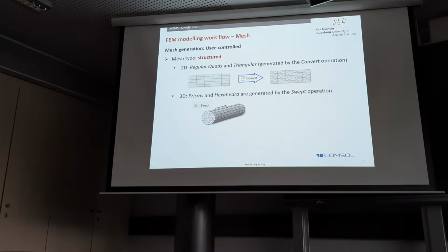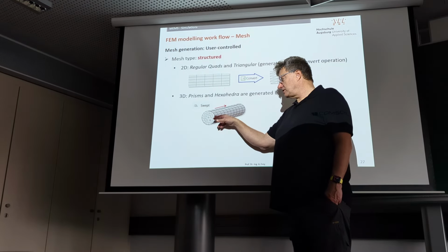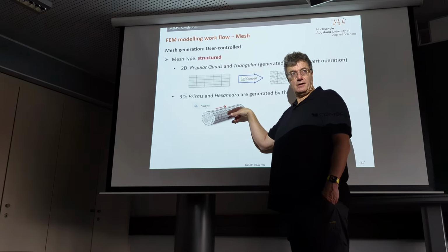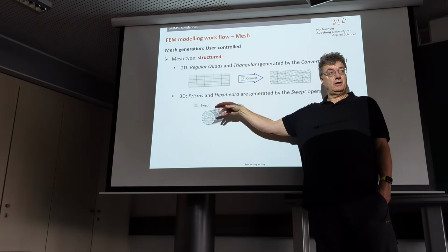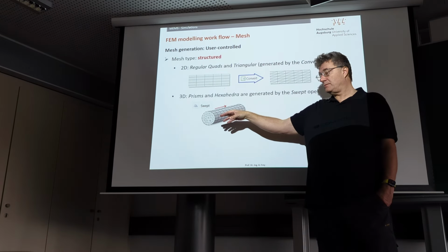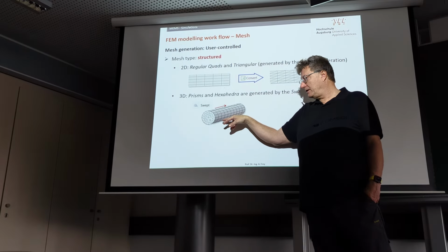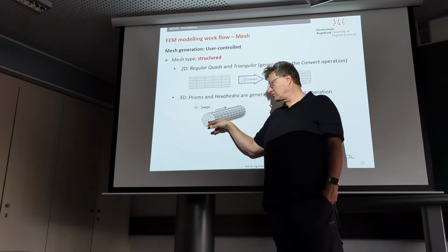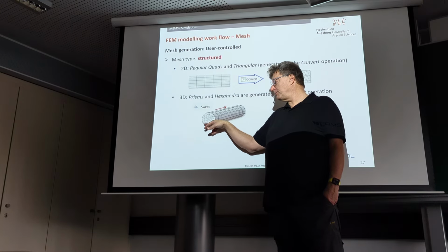That is always useful if you have a parameter which does not change very much in that direction here. For example, if that would be a simple CFD simulation, some flow going through that pipe, then it makes sense to resolve inside the cross section what has happened in the middle and what has happened on the boundary.